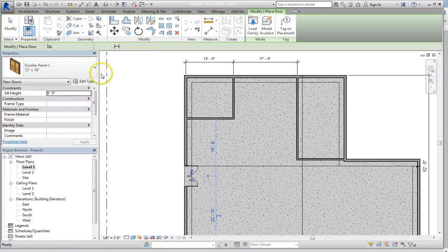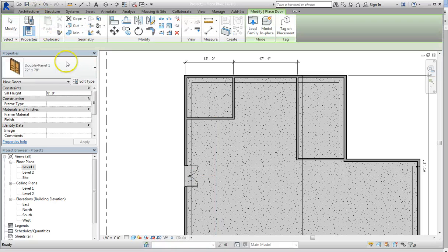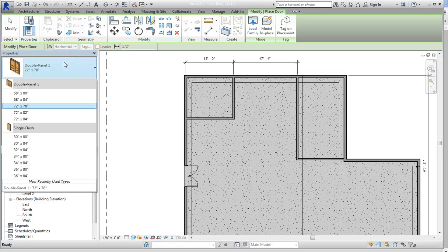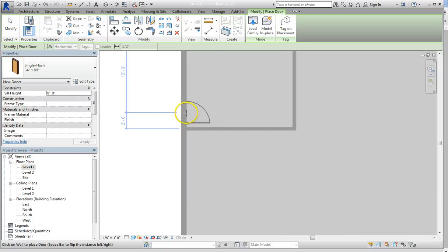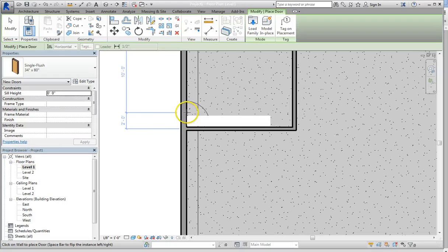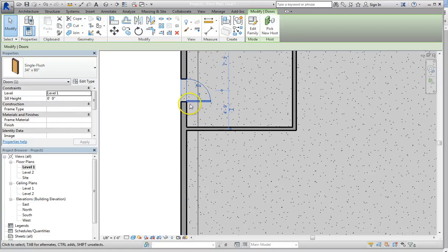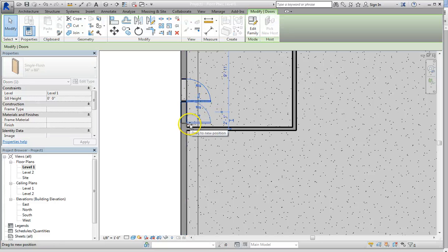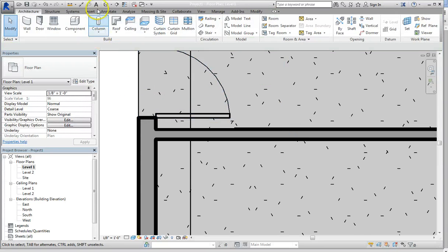We also talked about how if you want to have a door to a bedroom or a bathroom, it is most likely going to open up into a wall. So for example, you don't want to have your door be really far off a wall. You want it to be about 4 inches off. And there's a handy little measuring tool up here.